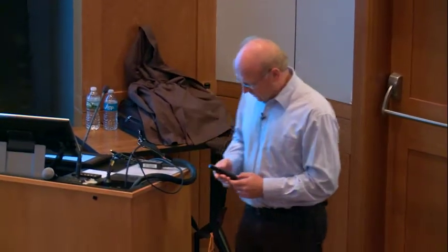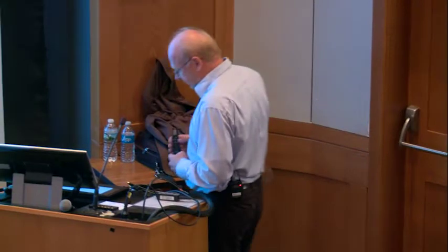Okay. Yes. Oh, here's another question. What are the restrictions when trying to go to higher resolution than the 200 microns you quoted? So what are the restrictions for higher resolution? You have to have something like, as I said, let's say 10 particles in your interrogation volume. If it goes smaller and smaller, you have to seed denser and denser.